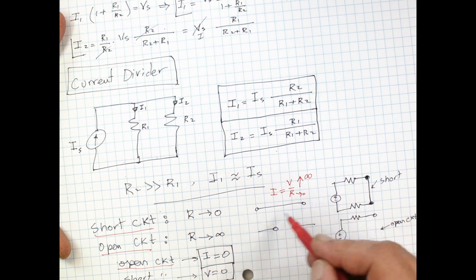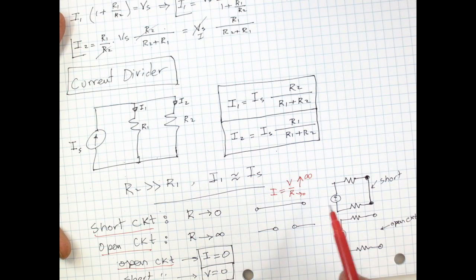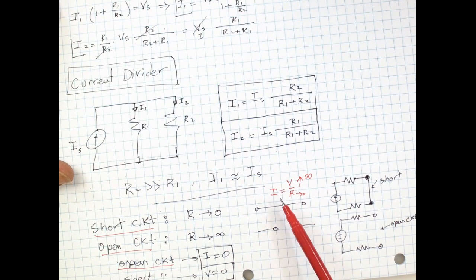So if you have a short circuit, essentially you're going to have an infinite flow of current through that particular branch. That extremely large current is going to turn into heat, and it's going to burn and cause fires. Of course, for safety reasons, we generally have fuses that will usually cut the electricity and open the circuit and prevent fires and disasters.